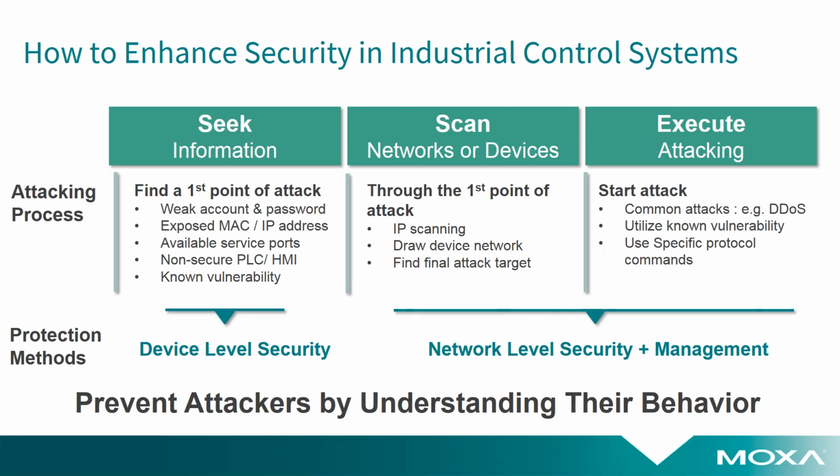So that could be devices that have the default username and passwords as shipped from the manufacturers, or you've got an exposed MAC or IP address out on the internet. You've left service ports available. You've got a non-secure, a legacy PLC or HMI that's not securable, or you've got known vulnerabilities that haven't been patched. So we're going to talk a little bit about device level security as one of the major things that you can do to try and minimize those weak entry points.